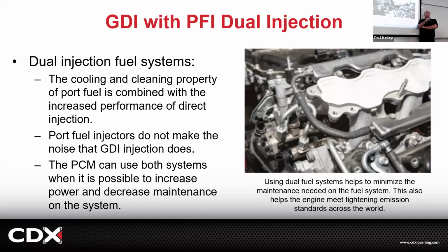We could do 1 injector for you, but if you come back with the cylinder imbalance code, you're going to have to do the other 5 and pay the labor again because we're going to be right there. You sure you don't want to do all 6 of them? So the customer declined, but he did 1 injector and actually it repaired it.